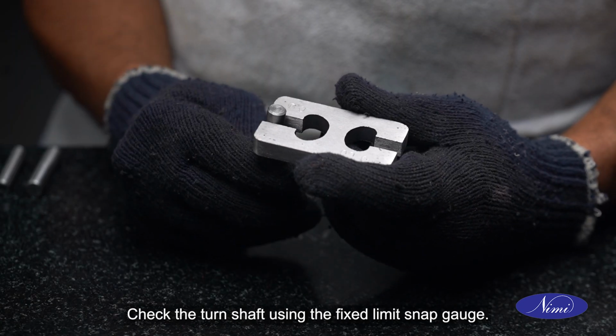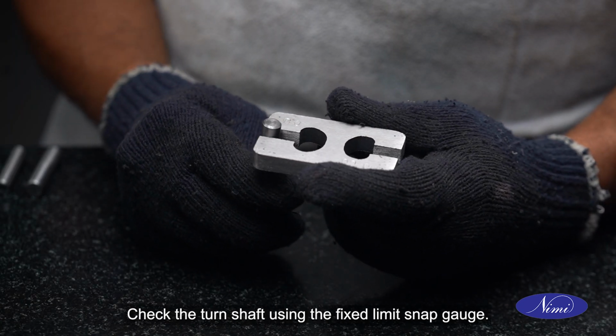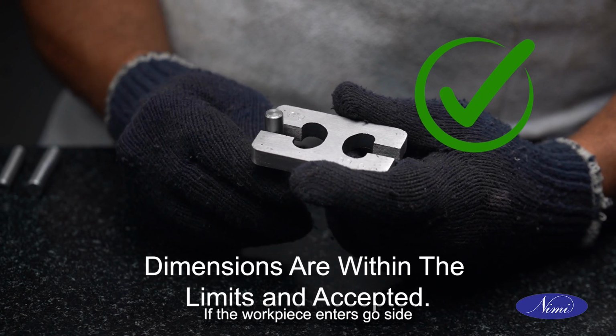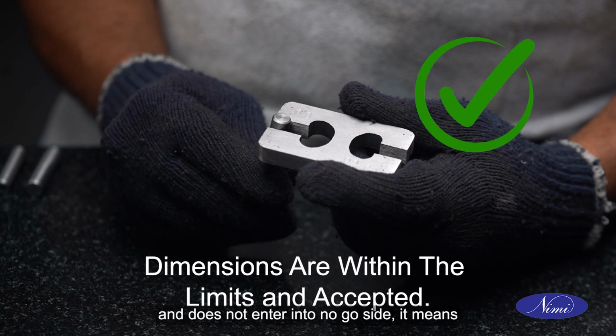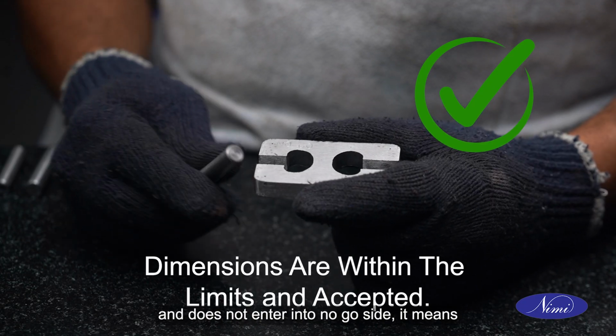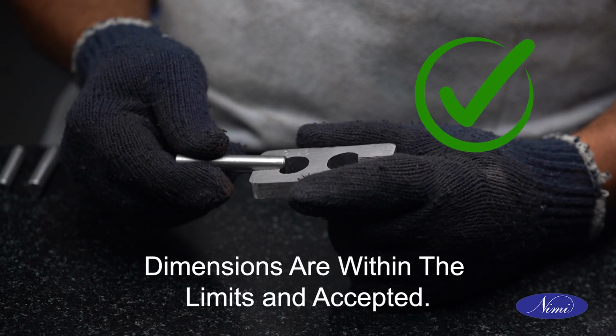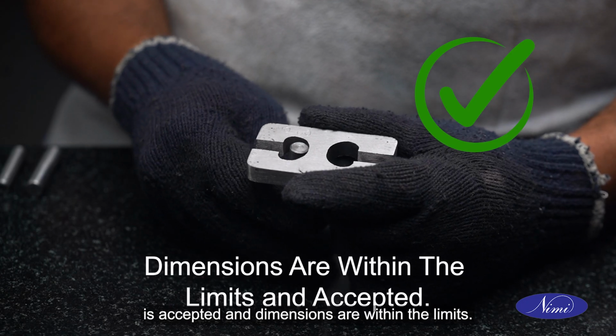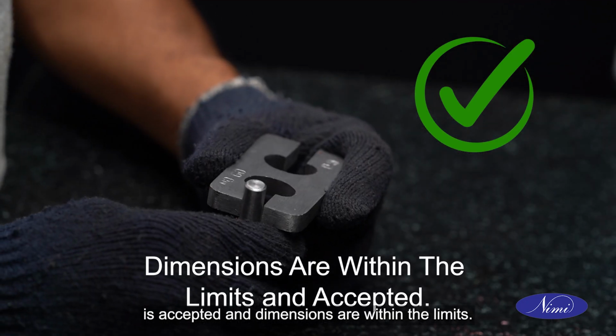Check the turned shaft using the fixed limit snap gauge. If the workpiece enters go side and does not enter into no-go side, it means the turned component is accepted and dimensions are within the limits.